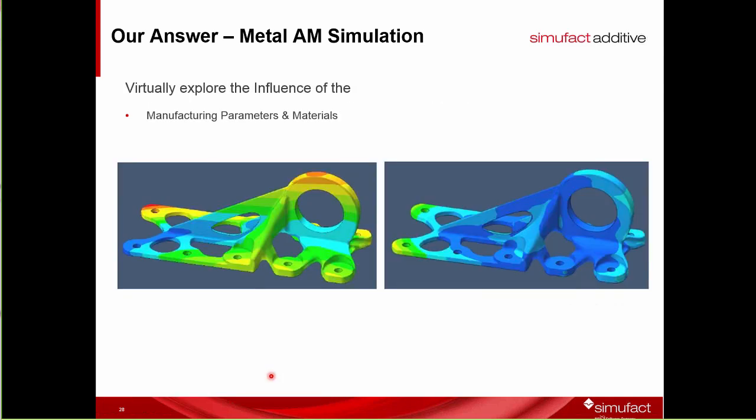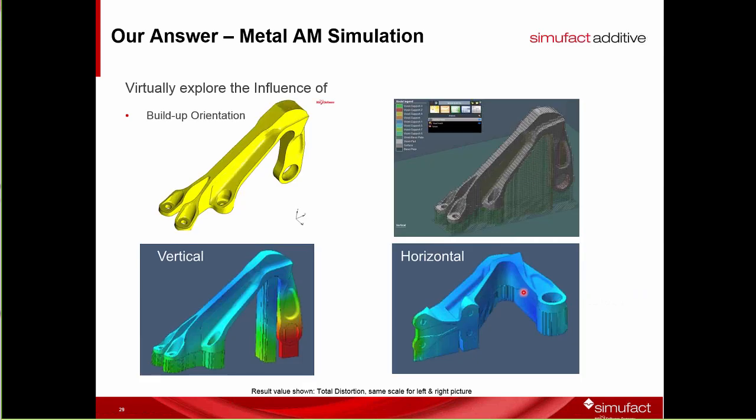So you could take a part, such as this aerospace bracket, and say, I'm going to have these parameters, therefore it's this set of inherent strain, and I get this simulation. If I set my parameters differently, I'm going to use a different inherent strain and get this configuration. In fact, this configuration results in lower deformation.